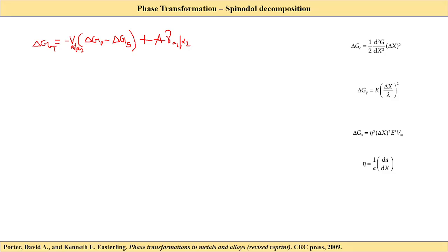That means you need to give 5 kilojoules of energy to some system to transform something, like to form a new phase of alpha and alpha, which is not a spontaneous process, right? It is not a favorable process. That means you need to continuously supply 5 kilojoules of energy to start the transformation. So that's what it is, right? And the best way possible is to heat it. You heat something, you give heat energy, and it will transform. That's what happens at high temperature phase transformations.